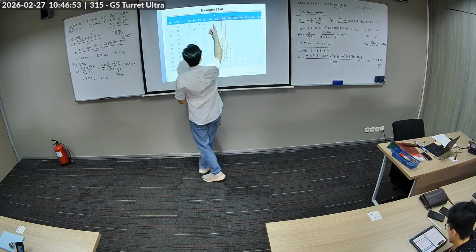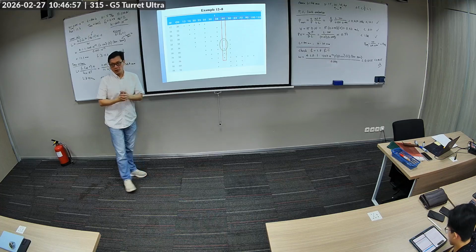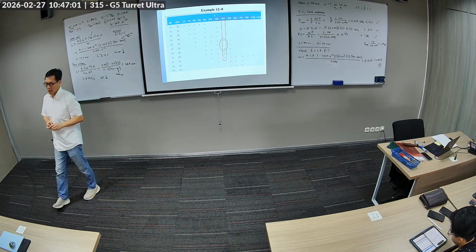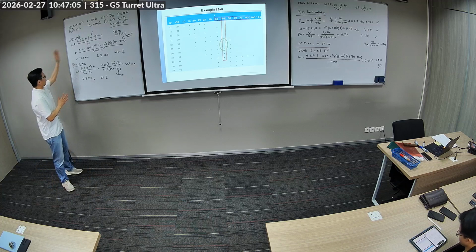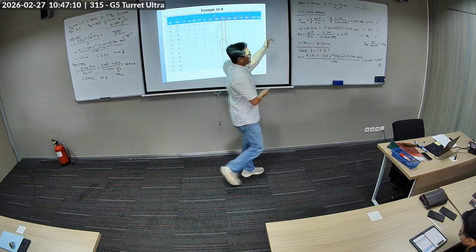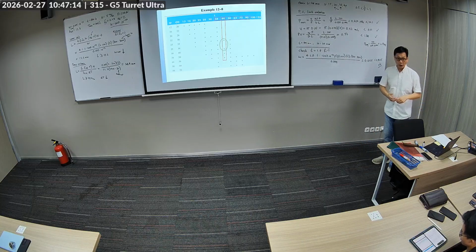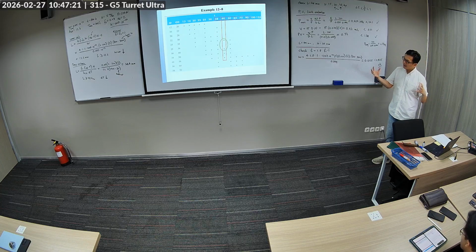Let's say you want a length of 30 times 2, like 60. You can always pick and choose from these catalogs. So to sum up, you have wear criteria, temperature criteria. You also have to check these 3, and if it all checks out, then you're good. So selecting components is like that. You got different criteria coming in, and you make sure you check all of them.